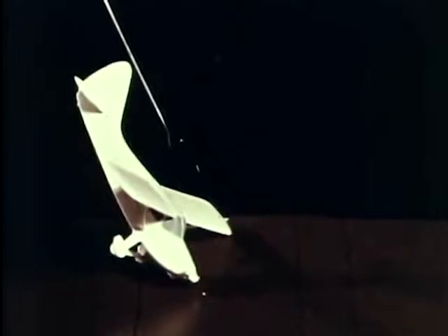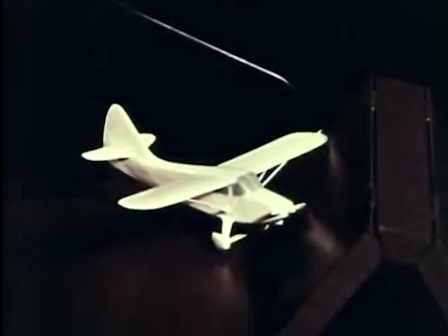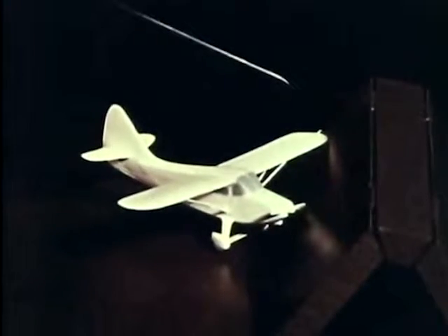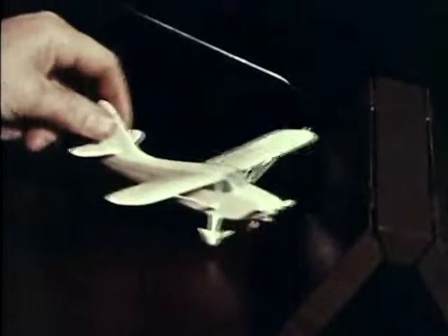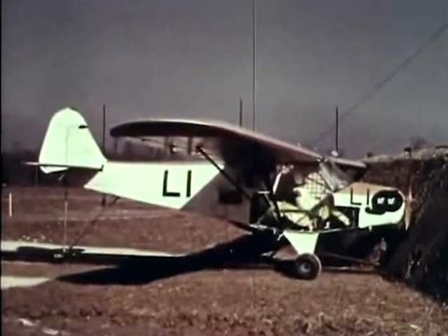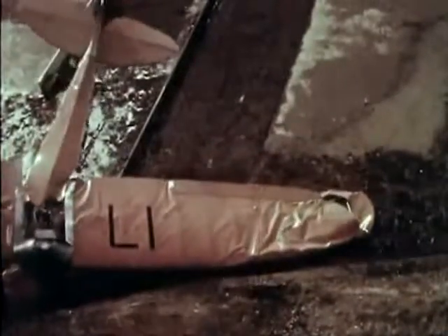in light airplane crashes. To simulate such a crash, the axis of the crash was rotated. The ground was simulated by a mound of earth, and the airplane ran along the ground in a level attitude to strike the mound of earth. The mound was located so that the airplane's left wingtip, left landing wheel, and nacelle would strike at the same time, in the same manner as in the stall spin accidents that were being simulated.